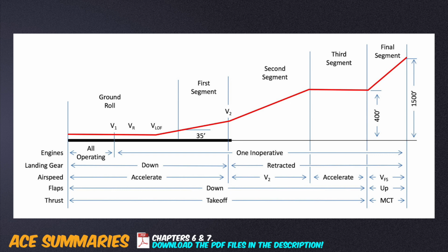An increased V2, also known as improved climb profile, is used if an aircraft needs to clear an object within the second segment. This procedure requires a greater takeoff distance or a reduced takeoff mass. Increased V2 procedures cannot be used when takeoff mass is field limited, because in this procedure, more runway is used in order to increase the takeoff speed.